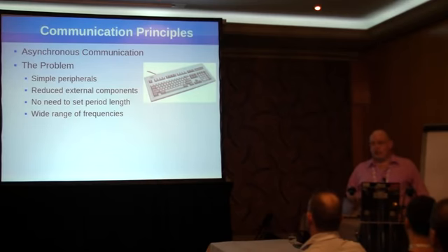It needed to be extremely cheap, so it needed to have very reduced external components, which in this case means no external crystal, no external oscillator, and it needed to be able to be plugged in and working immediately. So can you imagine having a keyboard in which you had to set up the baud rate on it before you could even use it? Doesn't work too well. And that was done on a lot of designs.